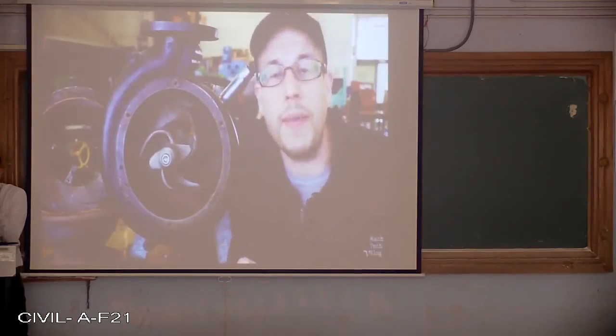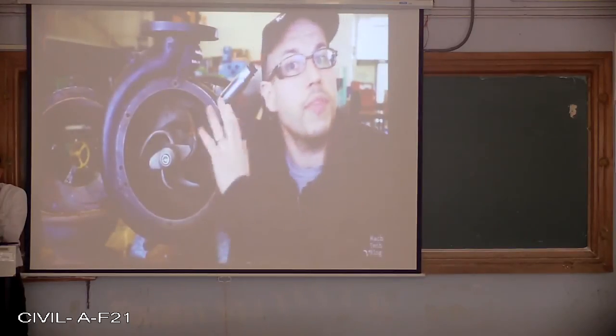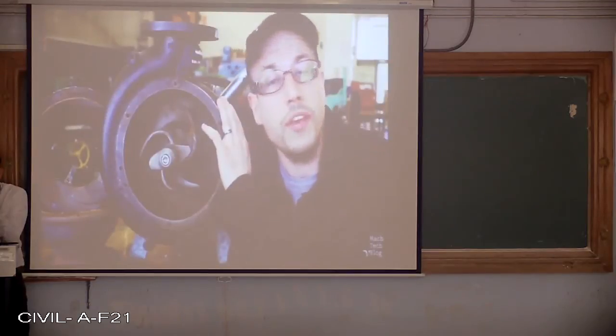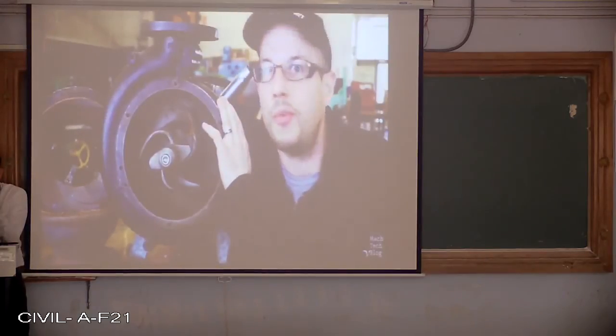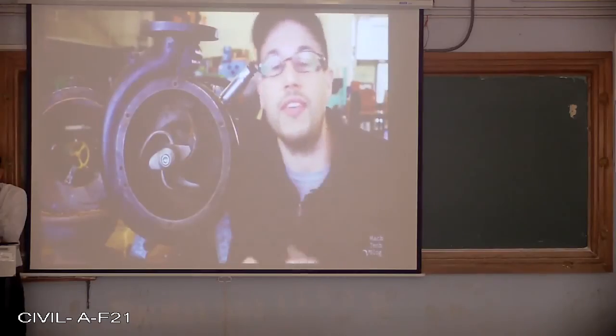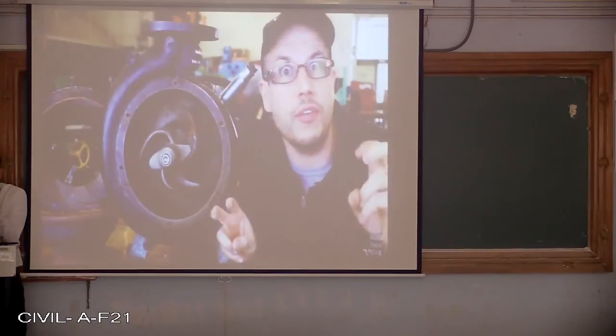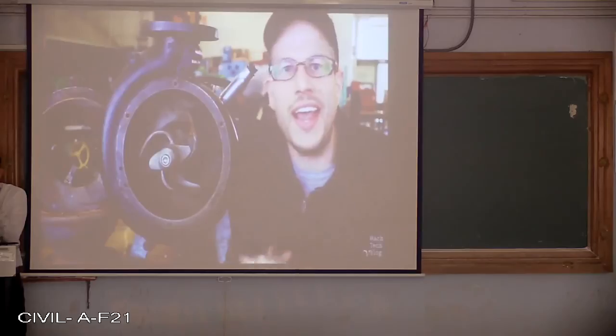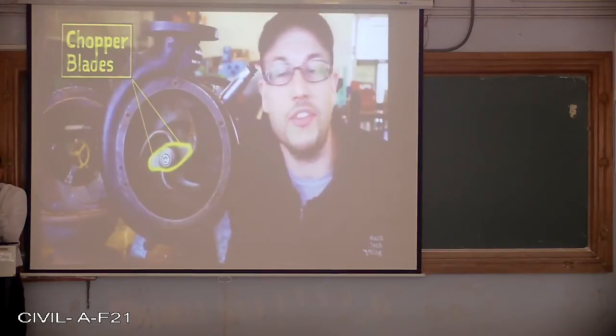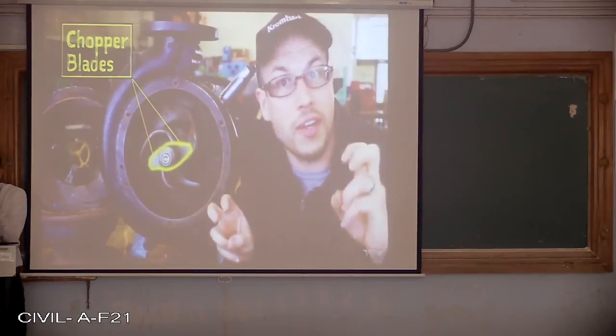That makes them ideal for trash pumps or this pump, which actually came out of a wastewater treatment plant where it was pumping raw sewage. It was necessary to handle gritty slurries with soft solids. And it even has special chopper blades just ahead of the impeller to help break down very large solids.